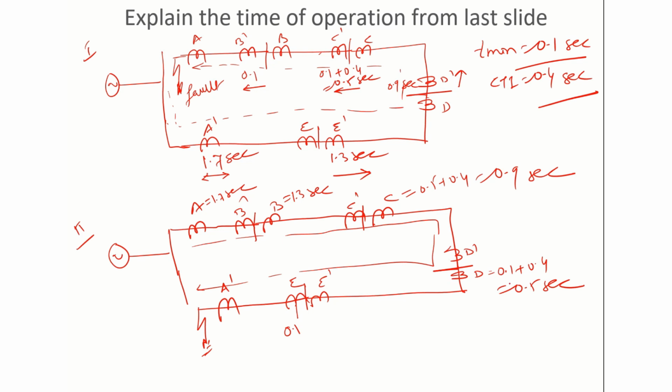But when this operates, there are two things. First, the fault will be isolated with delay, and second, it will cause a widespread disturbance. This thing we have already discussed in our initial sessions, so I'm not going to discuss it again. Now, if you see for this E relay, what should be the operating current direction? So this is my fault direction. So E relay should operate like this.